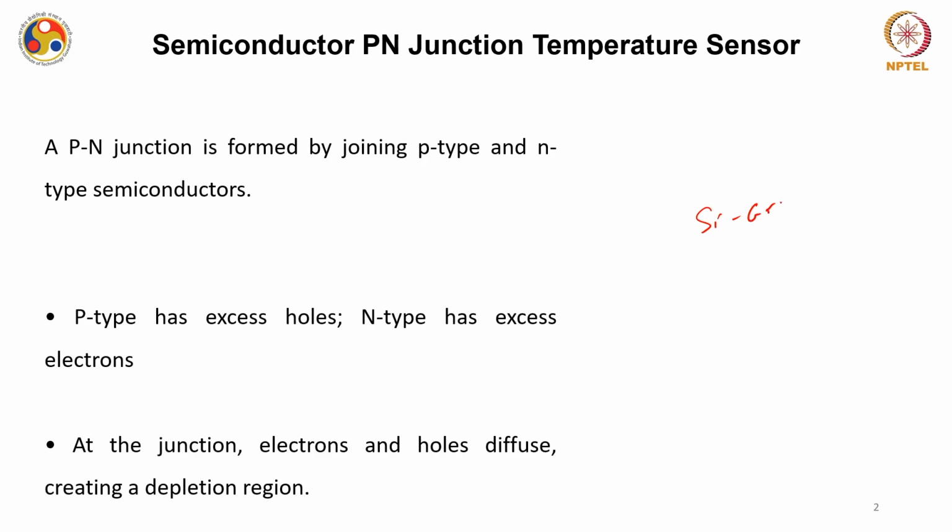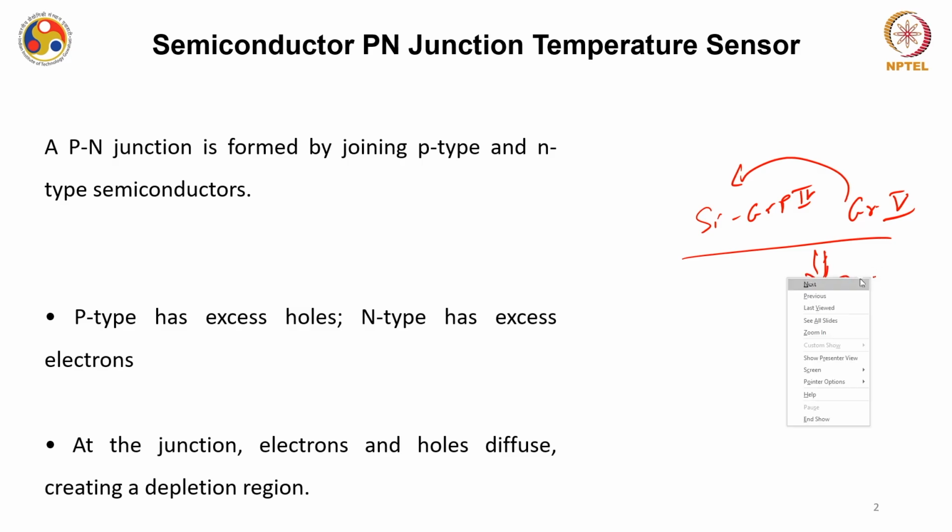So you know how a p-type semiconductor is generated and how a n-type semiconductor is generated, right? In silicon, when you populate it with electrons by introducing a defect in it, we generate a n-type semiconductor. Silicon is a group 4 element. If I dope it with some group 5 element, basically I am populating it with one extra electron, which makes it a n-type semiconductor.